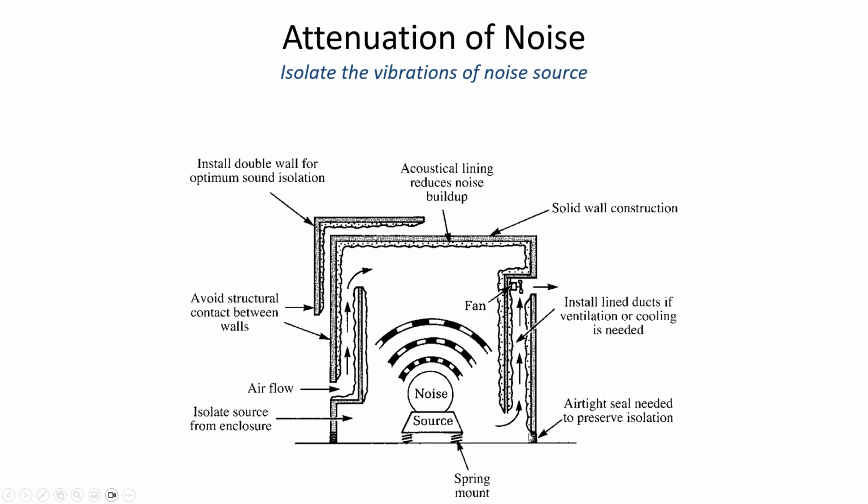And then the other part of it is just setting up barriers to intercept the noise waves as they emanate from the source. The problem being that a lot of times the things that are generating noise are also generating heat. And so we can't put them in a fully enclosed box, because whether it's somebody's heat pump at their house, it needs a lot of airflow without us trapping warm air around the heat exchanger. Otherwise, it's not going to get the house cool during the summertime, and if it's a heat pump warming up the house during the winter, you need to have plenty of airflow as well.